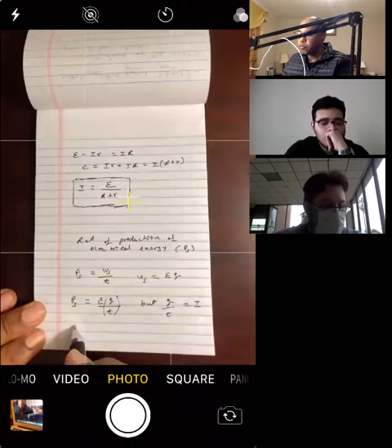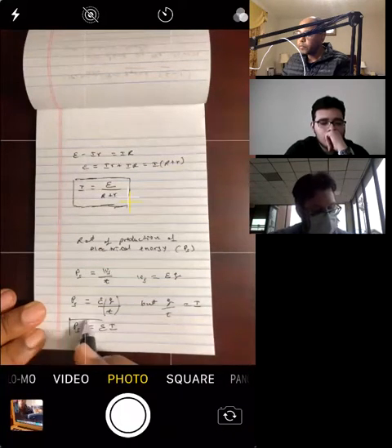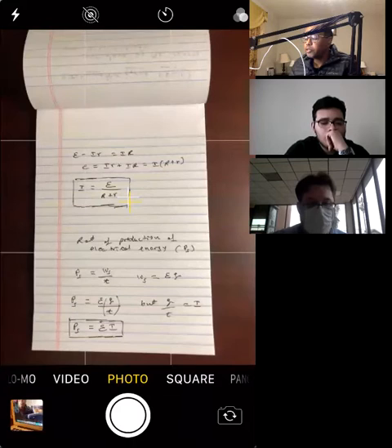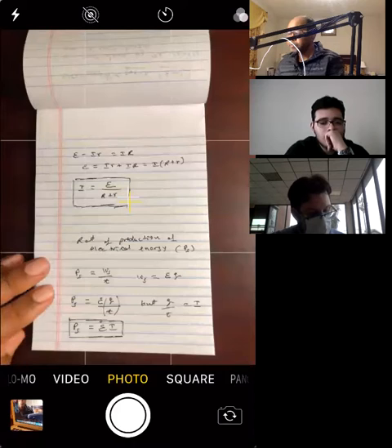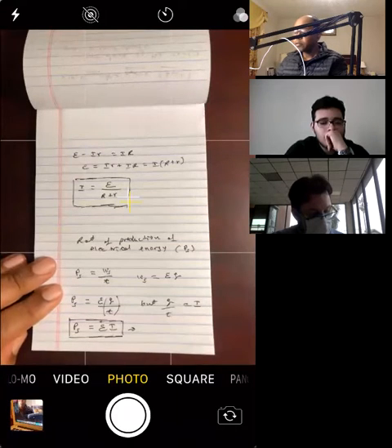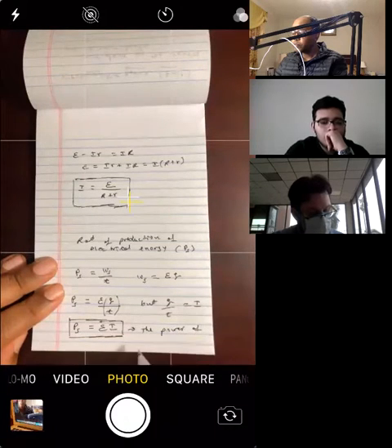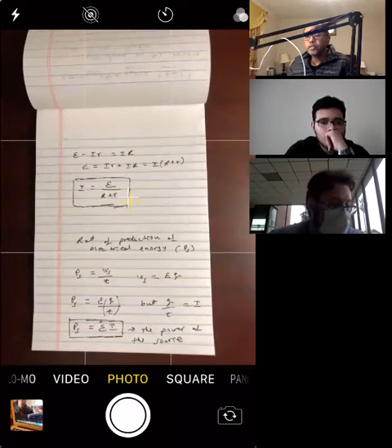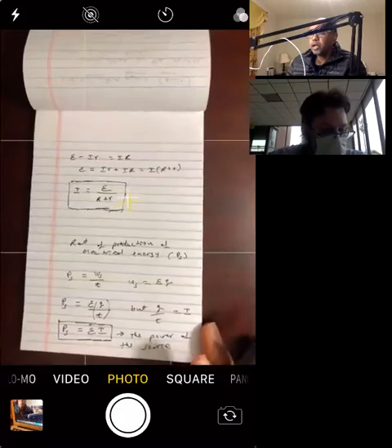So we have the following formula for the power of the source. It is EMF times current. The rate of conversion of non-electrical energy to electrical energy is simply the product of EMF and the current. This is the power of the source. This formula gives you how much energy is converted per second from non-electrical energy to electrical energy.